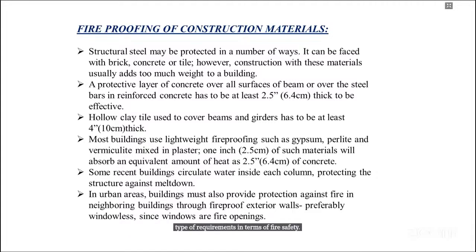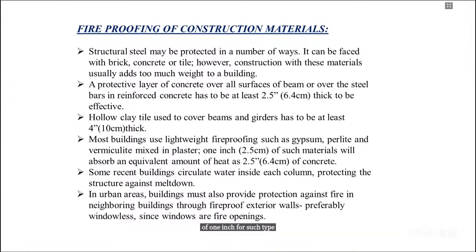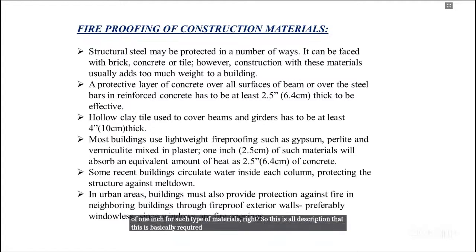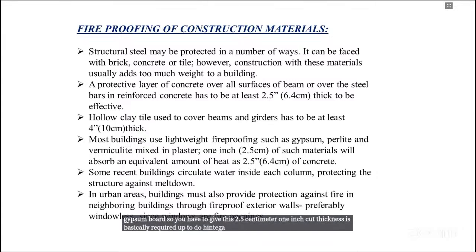Most buildings use lightweight fireproofing like gypsum, perlite, vermiculite mixed in plaster, of 1 inch for such types of materials, right? So this is the description of what is required as a fire safety material: this much thickness is actually required if you're using perlite or gypsum board. So a thickness of 2.5 centimeter, 1 inch, is basically required if you're claiming a 2 hour time lag.